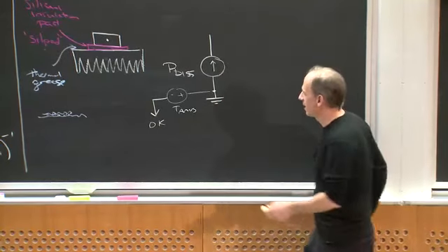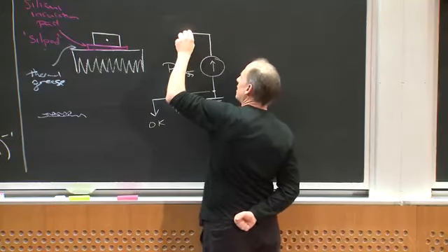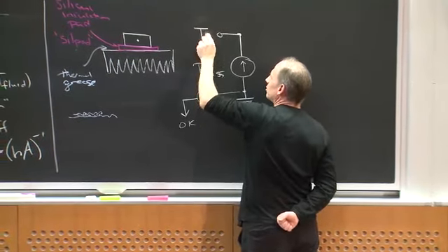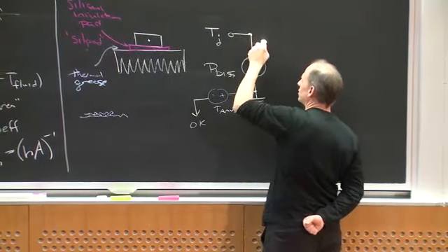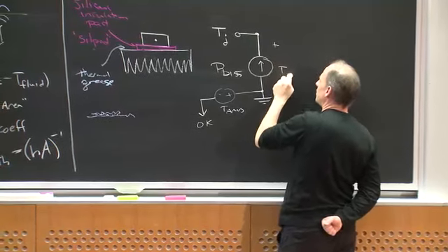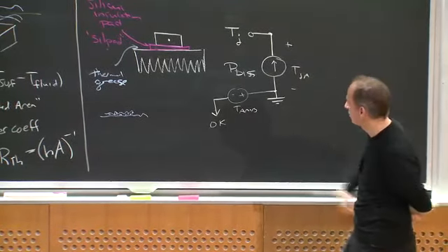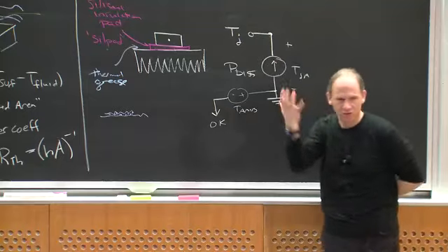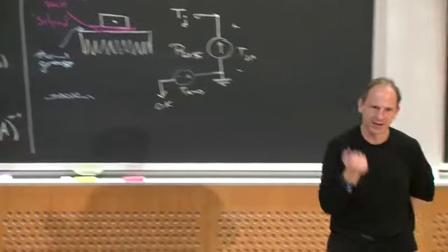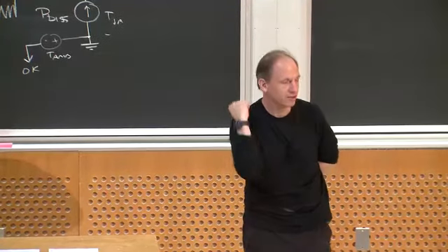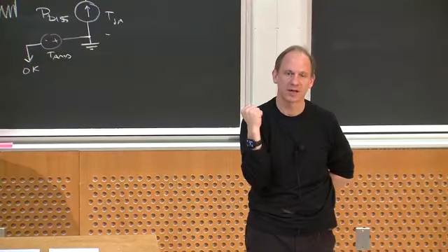That's the power dissipation, and we often say this temperature is at T junction, right? So it's either, this is T junction to ambient or T junction absolute, depending upon how I decide to write this. The junction is just my notion of wherever the power is being dissipated in the device. It may be an actual physical semiconductor junction. It may just be, wherever in this device is where the heat's being dissipated.